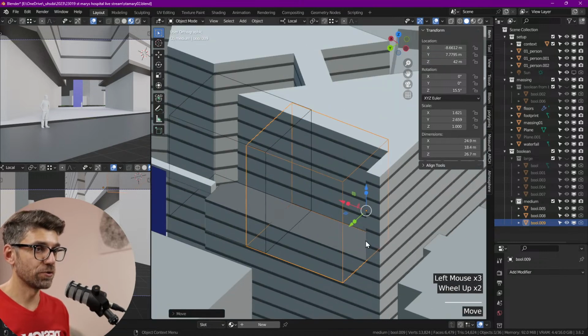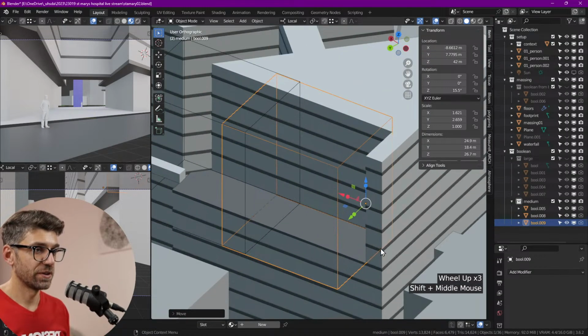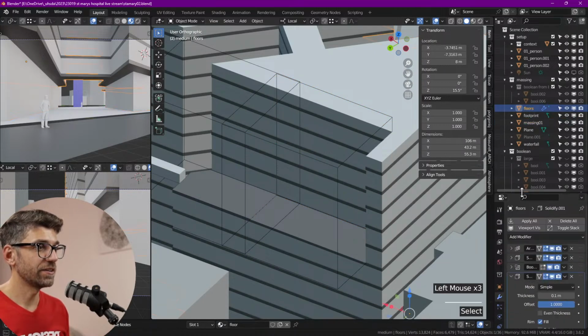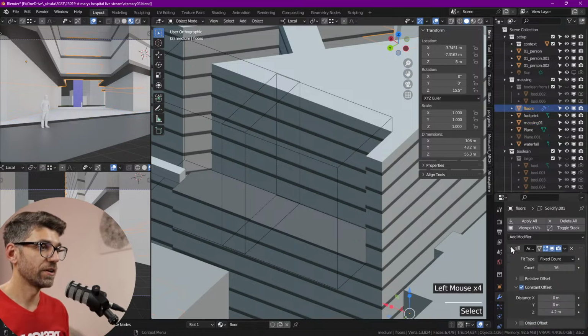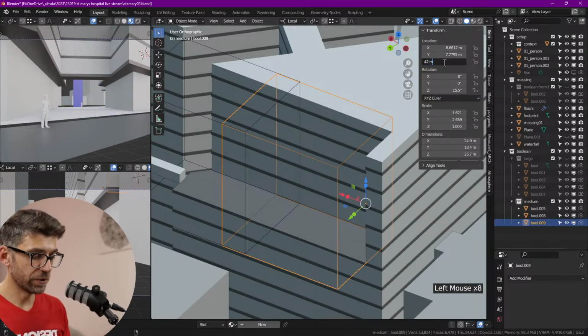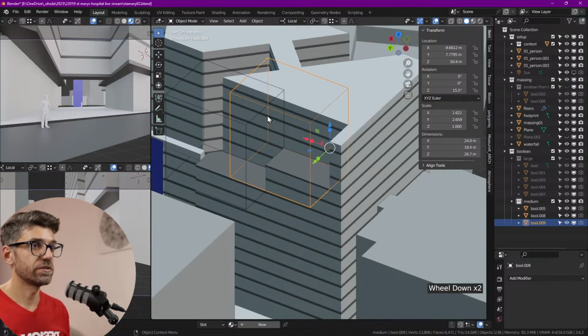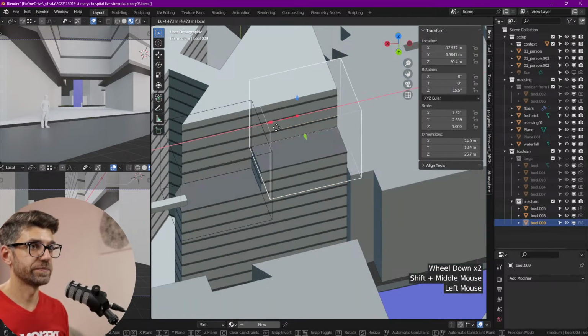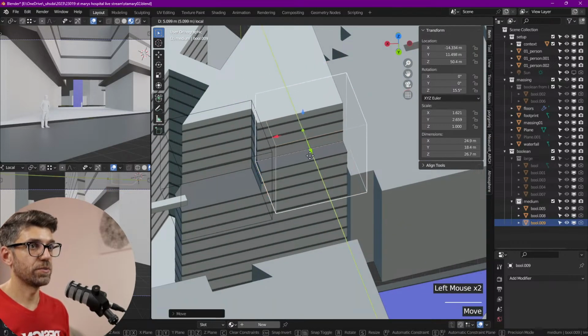So we'll start from 42 in here as well, and we're going to move 2 floors up. Let me just remember what we said. It was our floor height difference. If we go in here, array 4.2 meters, so 8.4 meters is what we want to move. So let's click on this. We can even go in here, I want to show you that. In here, I can type plus 8.4, right? And now we've got this nice setback happening over here. Let's move that out a little bit.